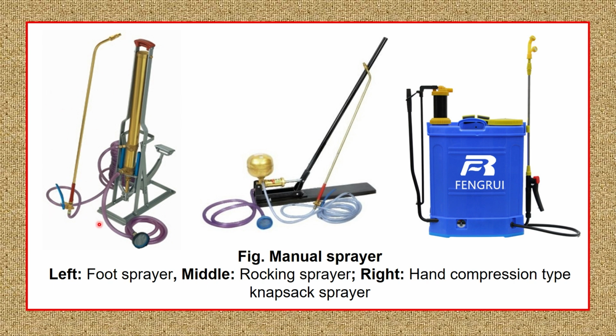So that's one advantage, that the sprayer has no need to carry the weight on the operator. He just handles the spray gun, whereas the other person who is staying out of the field will keep pressurizing continuously, and that's how the chemical will be sucked, and with pressure that chemical will be supplied into the spray gun.